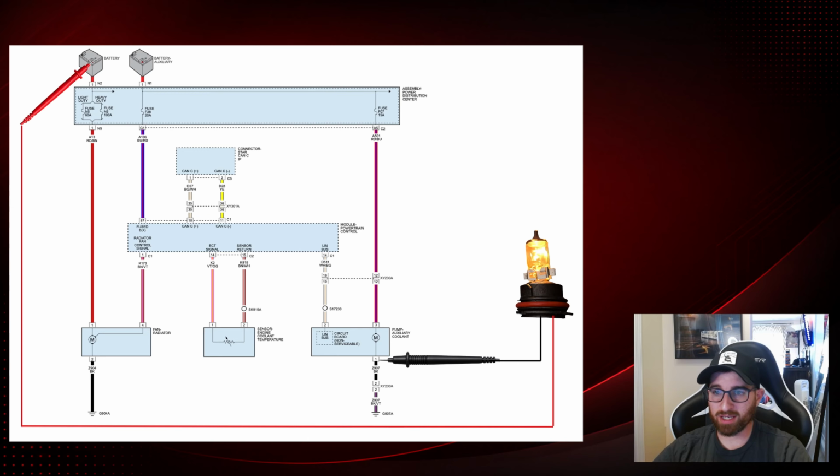You could do a voltage drop test on this or a couple other things. I just find this personally the easiest way. I have a headlight bulb, an 1157 bulb with some stackable banana jacks on it, so it's easy to put in the meter or put leads out of my bulb and do a quick little test here. I'll use various amperage bulbs depending on the circuit that I'm testing. So this is what I use for this one. This ground tested good, so I know I have no issues here.